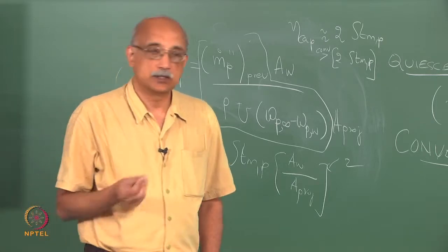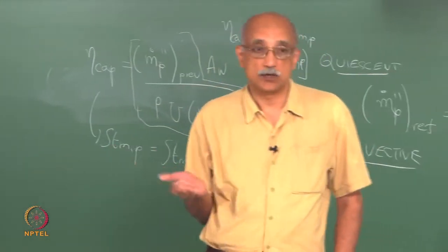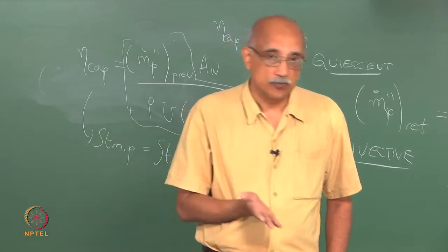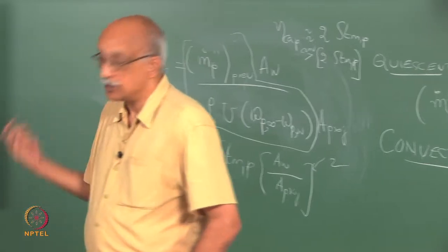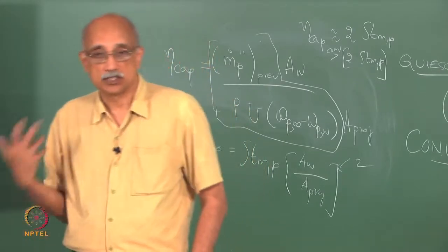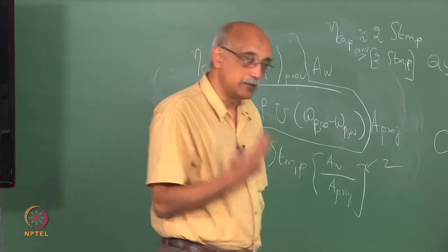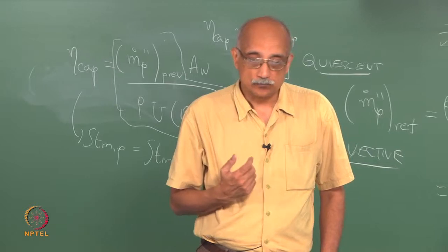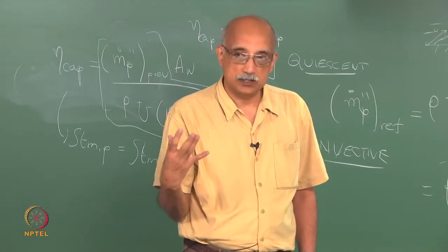The point again being that it is very hard to find particles of the same size in any real system. There is always going to be a distribution of sizes ranging from very fine to very large, and you have to have a way of representing this size distribution in tabular form or in graphical form. You have to be able to evaluate various mean diameters from this data and understand the implications of the differences in the mean sizes.